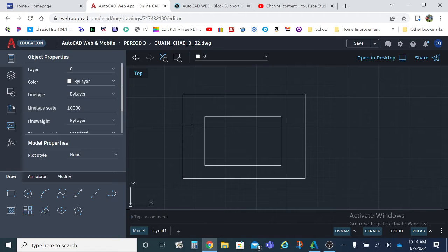When I talked about the trim command with you guys last time, did I go through shrinking a line or stretching a line, using the cut, using fillet, and setting the radius to 0? Does that all kind of sound familiar? Okay. So this time, did I also talk about using trim and then holding the shift key? No? Yes? All right. I'll go through and remind you guys about that.